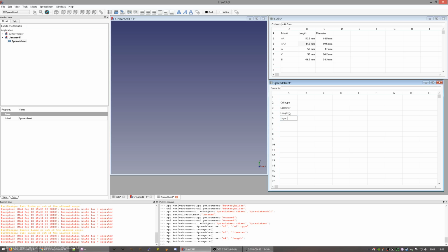a layer height, because I am designing for FDM, that's ordinary plastic extrusion 3D printing. And in that construction process, everything is actually printed as horizontal layers typically, so I want to calculate slopes such that the batteries will still roll. We'll have a bit of a margin just to make things move.